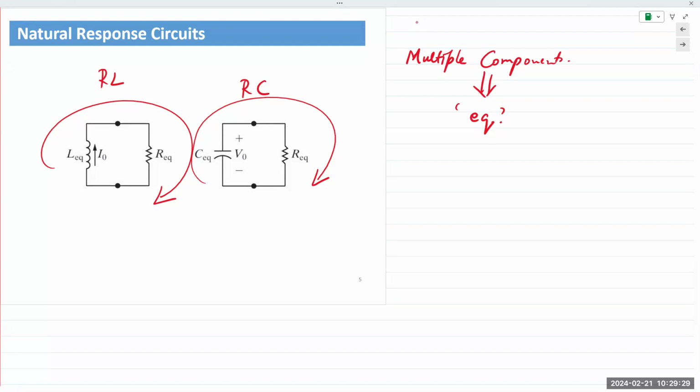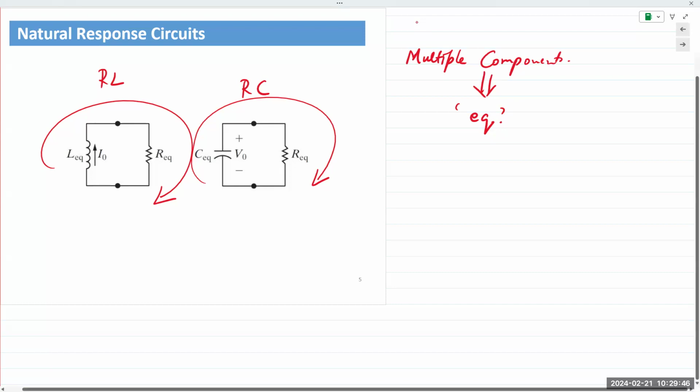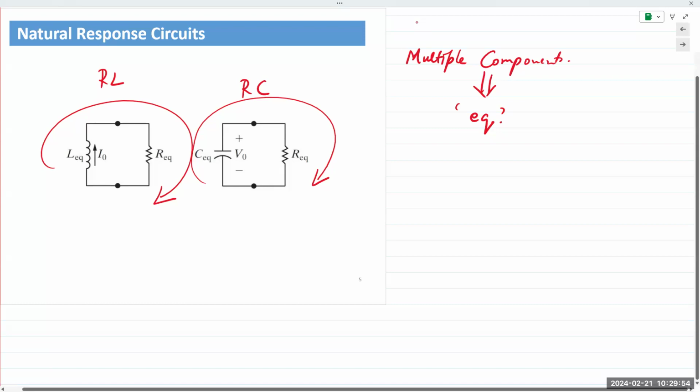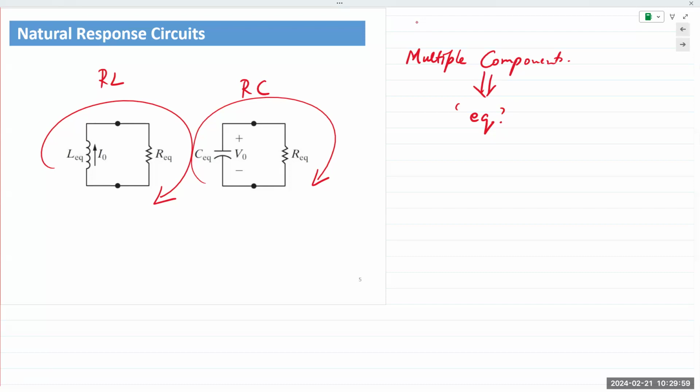A real life application would be a camera flash, especially the professional ones that are stuck on top of the camera unit. Sometimes you have 3 or 4 AA batteries. Once you use it, you might have heard a tiny whining noise. That is basically the capacitor inside it being charged. So again, a battery supplies constant voltage or constant current. But for a light flash, we want all of that energy released all at once, hence flash.